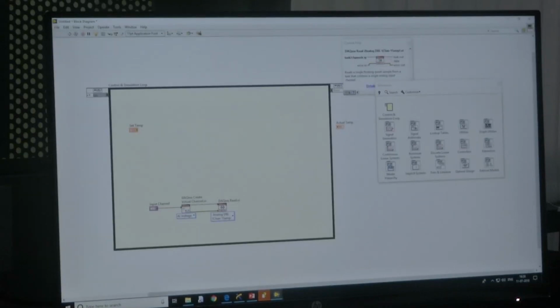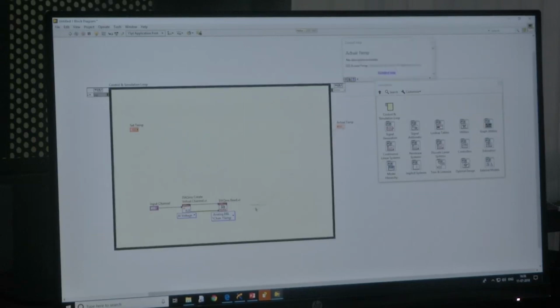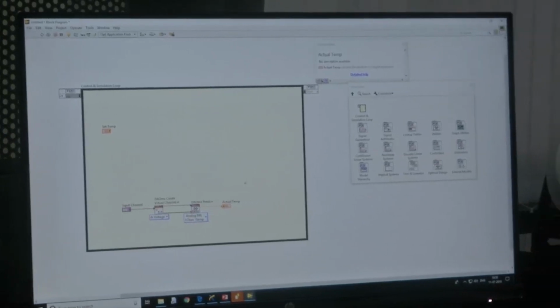So, the task or channel in has to be connected here, error in has to be connected here, and this is optional or recommended. Now, whatever data is there in the buffer will be displayed at this point, right. This data is nothing but your actual temperature data. This is our actual temperature, right. So, the output from the LM35, if I connect it to module 7, which is nothing but NI 9207, at analog AI0 plus and minus terminals, that value will be displayed here.